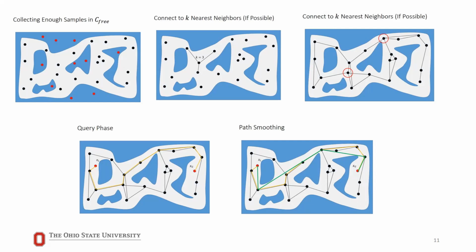What was question 2? And then how do you know that when you draw a line between the nodes that are created, it's not going around? So remember, there's a function that finds the closest path, and then there's a function that makes sure it's not going through the obstacles in free space. So you still have those 4 functions. So sampling, finding the closest path, checking if this path is available, meaning that it's not going to cross over the obstacles, right? And then the local planner connects them, so all of those now are connecting to their neighbors if your K is 3. So this is the local tree, right? Connecting, so eventually all of them become connected to each other.